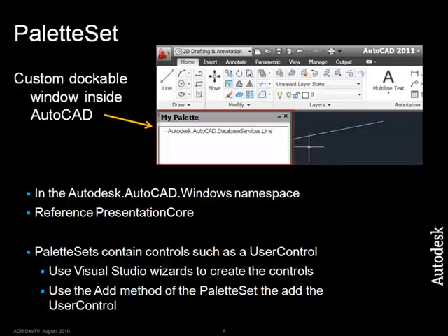Your palette set will contain controls such as a user control. You use Visual Studio wizards to create the controls, and then use the Add method of the palette set to add the user control to the palette set.